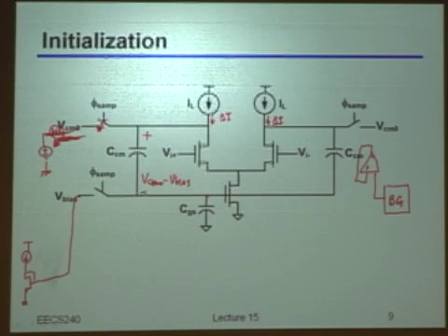And for having low impedance there, that's going to cost you power. And that's normally some power that you would not like to spend, just because indeed you are spending power to create a small impedance to sink the amount of current without disturbing too much the common mode. But that's only power spent for biasing. It's not power spent for useful operation of the amplifier, right? So you're not going to use it for settling or for something else. So it's normally something that we don't really like, right?